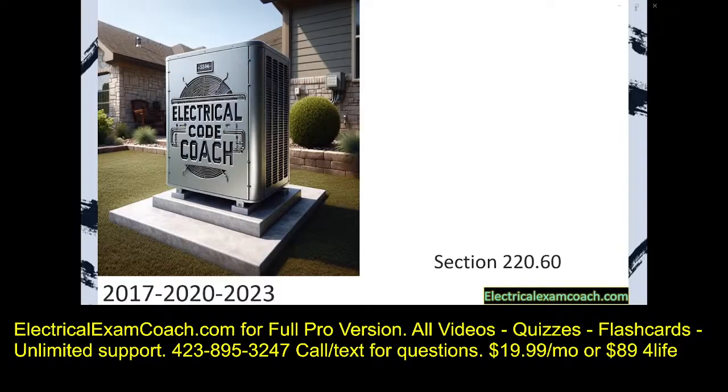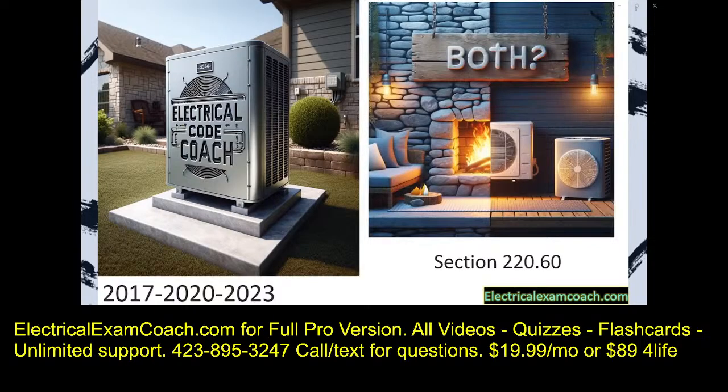Today we're going to be calculating HVAC VAs for our heating, venting, and cooling. The only code that we need to be familiar with is 220.60, and that's talking about non-coincidental loads. Let me explain what I mean. Usually in a typical house, you're not going to be running the heating and the cooling at the same time. So the code has made provisions for our whole house load calc that we only have to count the larger of the two. Let's get to it.